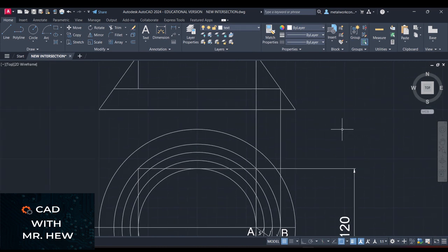So I'm going to draw a line up there. Let's turn on this. Enter. Since we're just going to follow through, we're going to draw the horizontal disc here. Good. I'm going to trim. We want to keep our drawings clean. As I said, if you're using a traditional T-square or set square, pencil, French curve, and erasers, you would just leave the line, because that would be a 4H construction line. But in AutoCAD we want to keep it clean, so I trim it. You could let it stay, but the drawing looks neater.